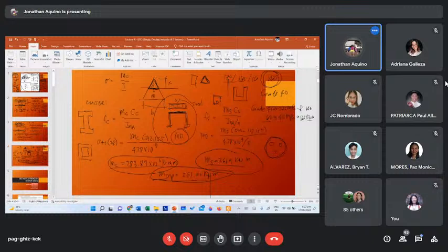hollow section. So yung hollow section, ito ginagamit sa mga if there are cases na sometimes merong mga lines, mga electrical lines, o kaya communication lines na kailangan natin i-protect pag magamit tayo ng hollow section. Or sometimes voided, mga slab. So may mga cases na voided slab. Okay? So the purpose of this is to reduce the weight of the beam o the slab o the structure.